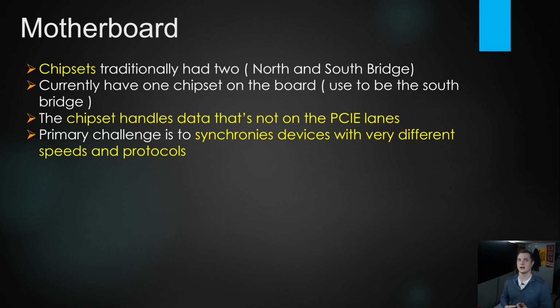So there are motherboards out there, and actually most of them, where those PCIe lanes are not wired directly to the CPU, it's actually wired to the Southbridge. So in theory, you can put your GPU on the bottom PCIe slot, but you're going to get a little bit worse performance, particularly from latency, than if you put it in the top slot, which is wired directly to the CPU. Now you can get around this with your enthusiast level CPUs, because most of the time the motherboard has all the PCIe lanes wired directly to the CPU.